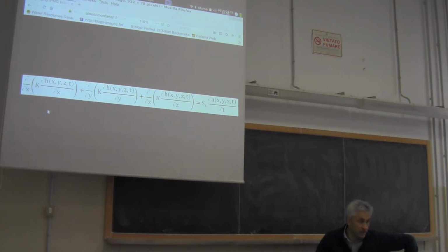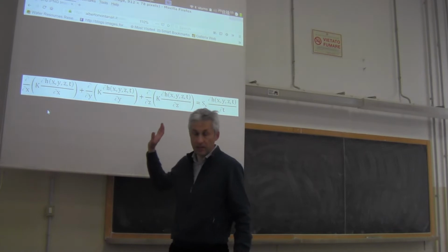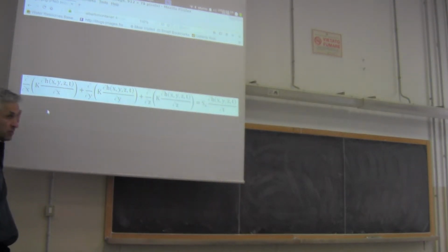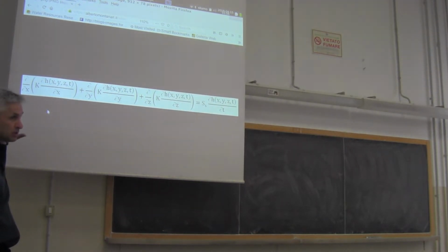And the minus sign has disappeared, because if you remember, these terms on the left-hand side were negative, if you check on the web page. Now I can put Darcy's law in and everything becomes positive. And now we have only the head that is unknown, which is fine. Remember, we eliminated the flow from this equation.